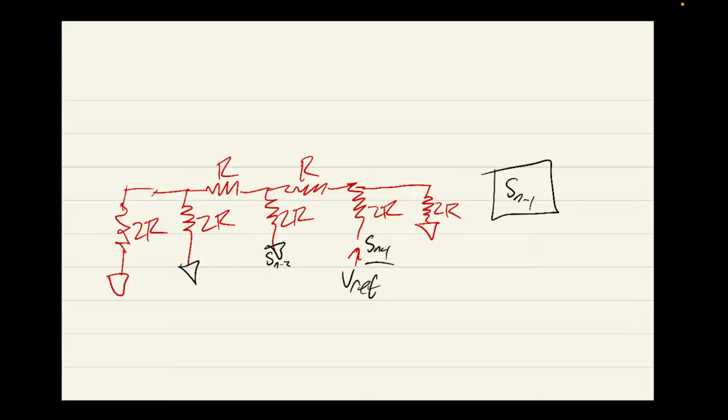When we ground all of these, we get the very cool pattern. We can pretty much section off every area going to the left somewhat sequentially and see a little pattern. So I noticed that these two R resistors simplify to a single R resistor. So going this way, it's as though there's just R. If I look this way, 2 R's in series, I get 2R, R, 2R, and then I get to my first kind of more complicated area, because now I actually have the voltage to accommodate for.